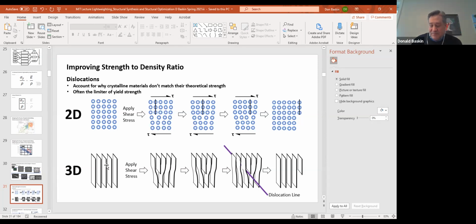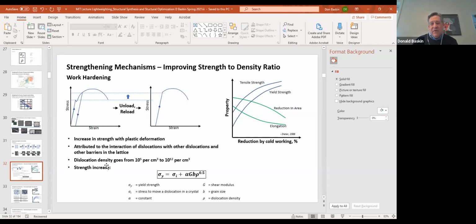So really small. I think this is right around where we stopped off last time. We were going to go into some of the strengthening mechanisms, and how you can slow down or make it more difficult for these dislocations to move through a lattice of atoms. If it's difficult to move a dislocation through the lattice, that's the same thing as strengthening the material, because it's not going to deform by moving the atoms without dislocations, since that takes way too much energy. So how can you make it more difficult for these dislocation lines to move through a lattice of atoms?